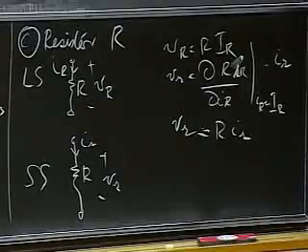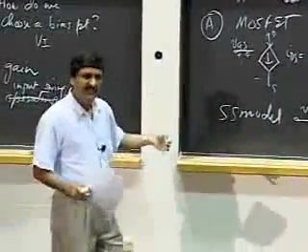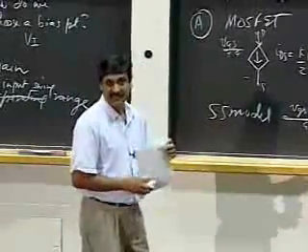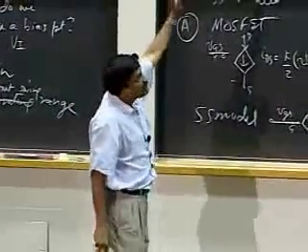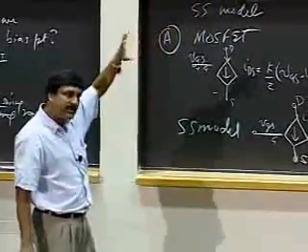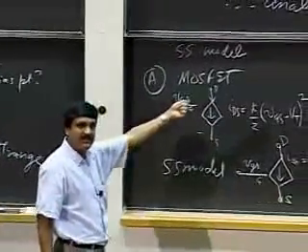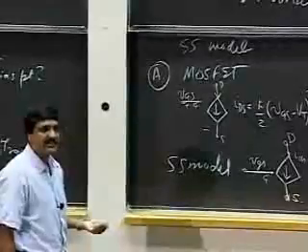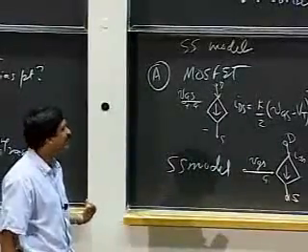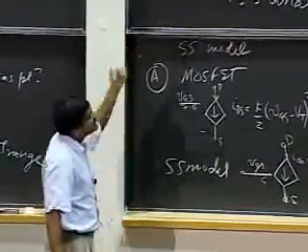So what I've done so far, let me just take you through where we are right now, give you the big picture here. I began by suggesting that I'm looking to find an even simpler way to do small signal analysis. I gave you an informal proof to show that if I had small signal element models for all my elements, I could simply replace them in the circuit and then do a corresponding linear circuit analysis to get the result I'm looking for. So there are 3 steps to the method. And as a first step, we began by finding small signal models for each of our elements.